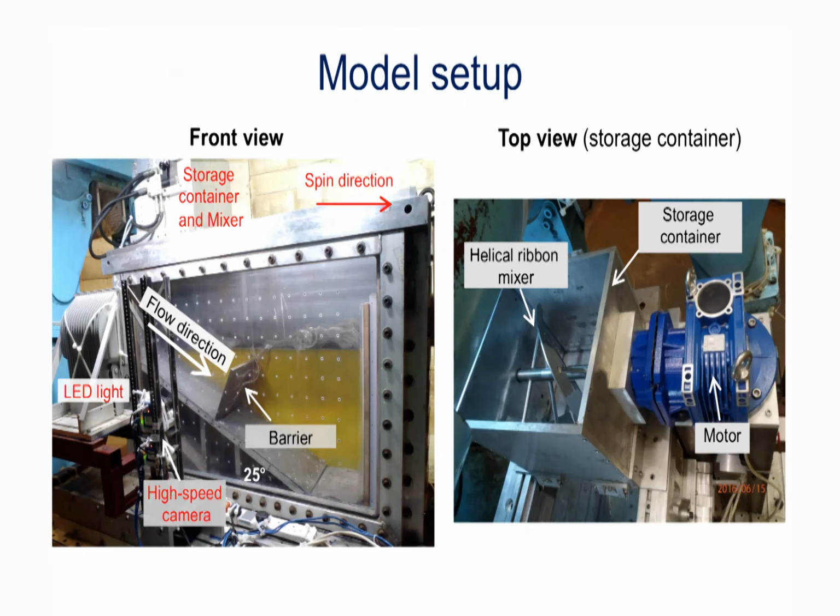A storage container and a model slope and barrier are installed inside the model container. A new flexible barrier model was developed for the study. The new model consists of a rigid post with 4 cables. A net or membrane can be installed on the cables. The spring elements are responsible for controlling the load displacement behavior of each cable. The displacement is captured using laser sensors, while axial force is captured using load cells.